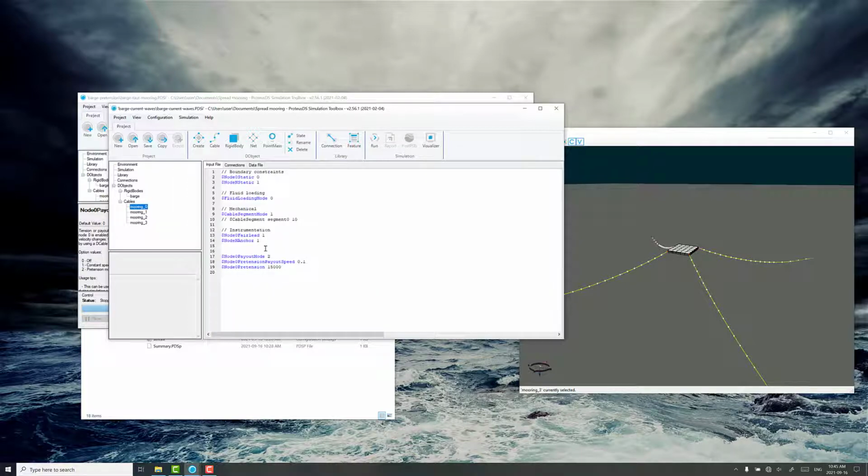But before we do that, make sure you turn off the pretension mode. You can either set it to 0, or just to be really sure, just delete it straight out of the input file. We don't want the pretension to be fighting any environmental loads, because it'll be actually paying out line or paying in line when there's environmental loads going on. So we don't want to do that. That's for the wind, current, and waves load case. Always good to do that before you forget.